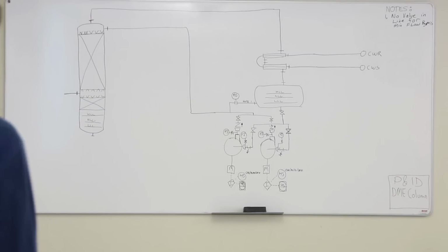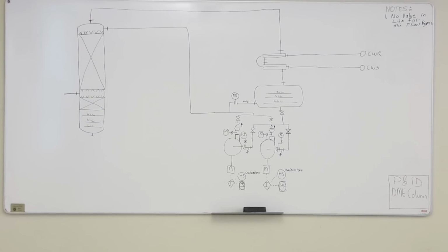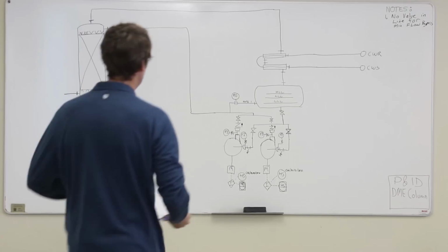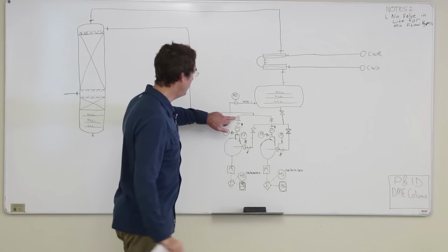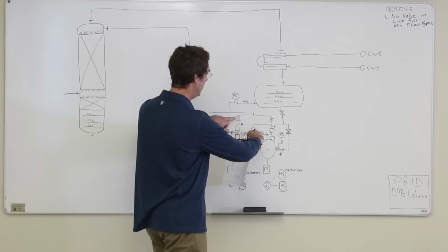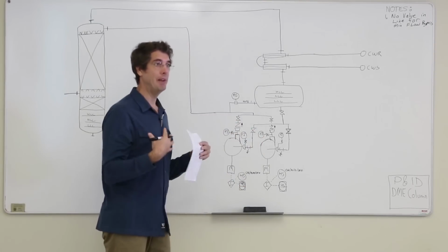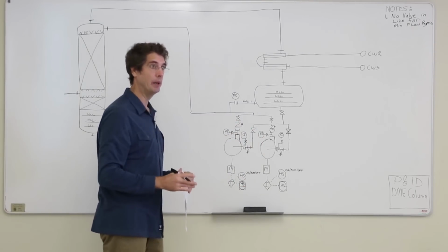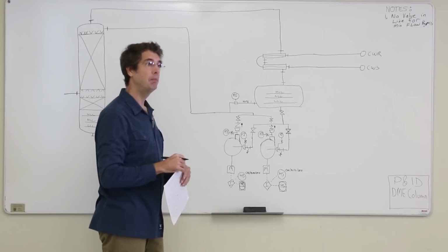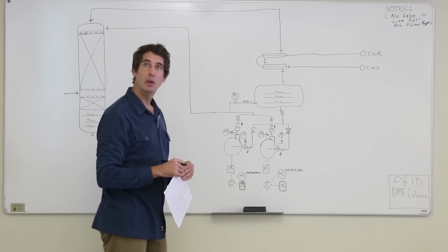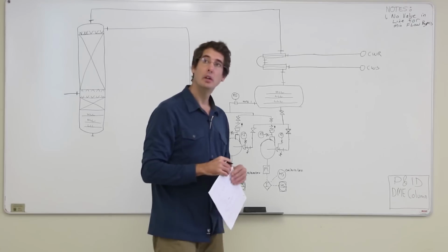No, that valve there is the actual isolation valve. So if you close this valve and you close this valve, now you can take the pump out and do maintenance on it while the system's actually operating. Liam? What's the valve after the pressure indicator before the strainer?